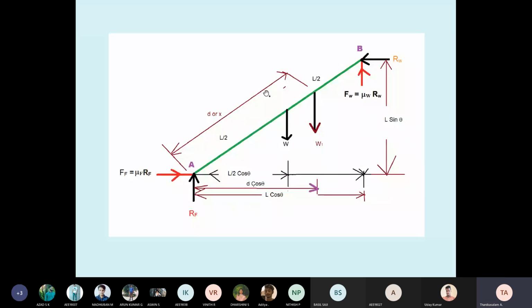See, this is called a free body diagram of the ladder, students. The ladder is touching at two places, the floor and the wall. That gives reactions. I introduced RF, vertical upward. Why vertical upward? Because the ladder is touching the bottom.